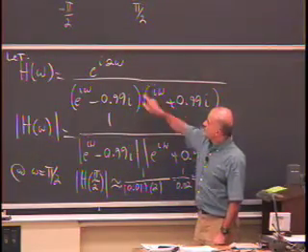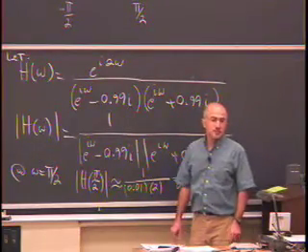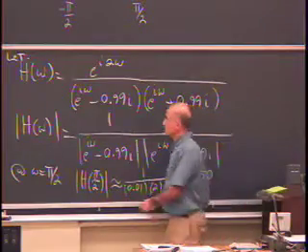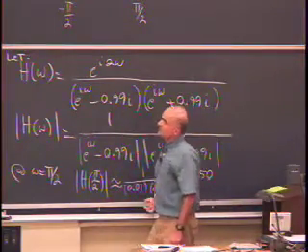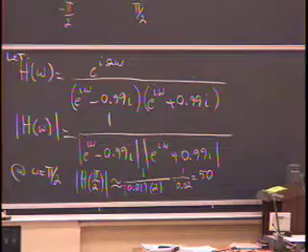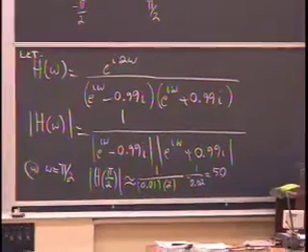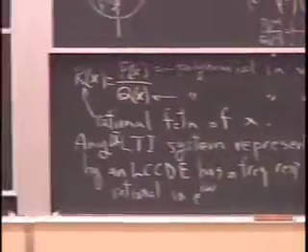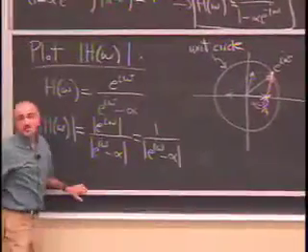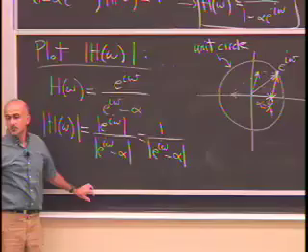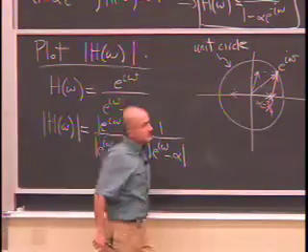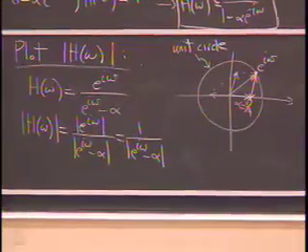Now let's see what the difference equation is that represents this filter. How do I find it? Here, to find the magnitude response, I multiply top and bottom by a sufficiently large power to get rid of all the negative powers of e to the i omega. So what do I do there to get a difference equation with only delays in it?